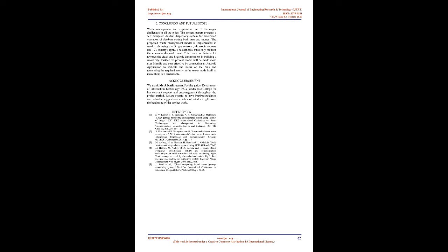2.6 L293D motor driver. A motor driver is an integrated circuit chip which is usually used to control motors in autonomous robots. The motor driver acts as an interface between the microcontroller and the motors. The most commonly used motor driver ICs are from the L293 series such as L293D, L293NE, etc. These ICs are designed to control two DC motors simultaneously.